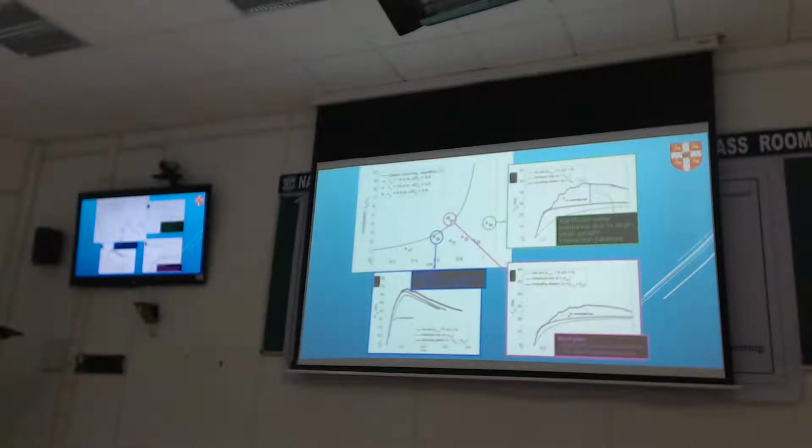Then you push it quite far away. And this is not a realistic case. Obviously, in reality, you will never design piles to be close to their buckling load. But you can see if you do that, your soil is now contributing so much to the resistance offered to the movement of the pile.